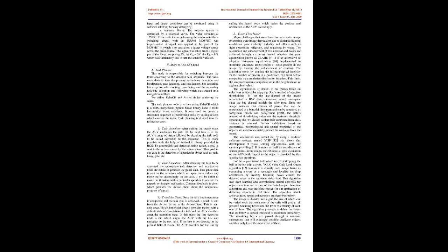Software system. A task planner. This node is responsible for switching between the tasks according to the decision task sequence. The tasks were divided into the primary tasks: buoy detection and localization, gate detection and localization, bin detection, bin drop, torpedo shooting, resurfacing, and the secondary task line detection and following, which was treated as a navigation method.